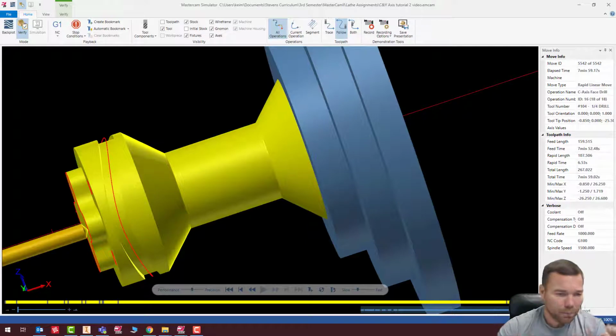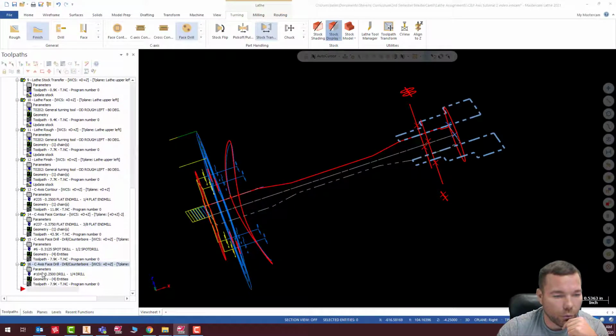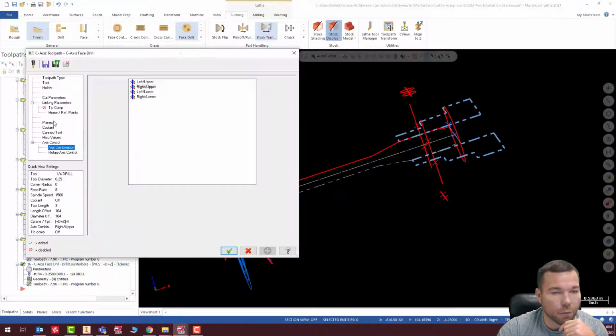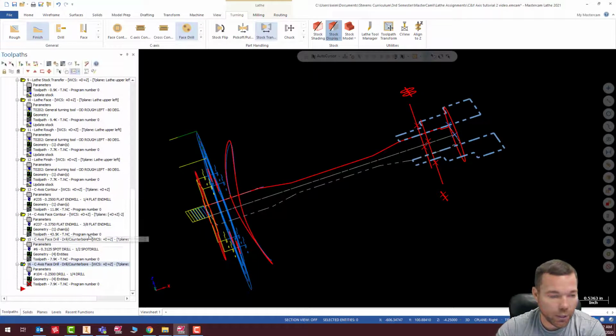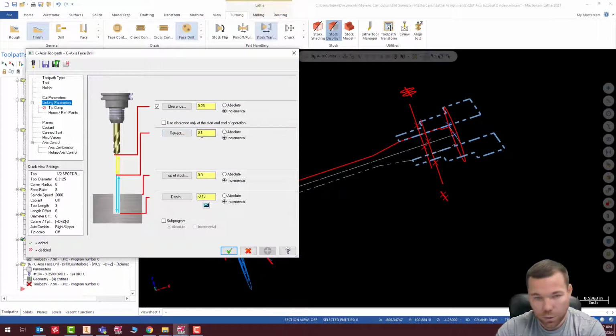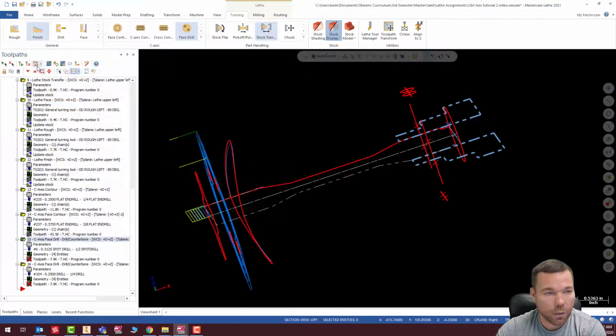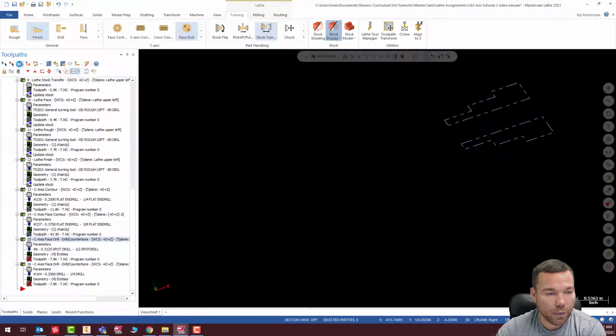So one thing I will do before I go is I'm going to go in there just for thoroughness, that linking parameter, and I'm going to make that retract 0.3, 0.3, check, and I'm also going to do it for this one as well. 0.3, 0.3, check. And I'm just going to regenerate that.